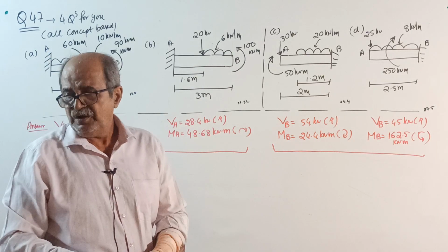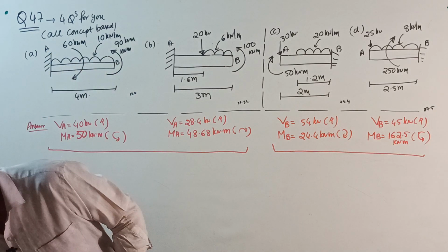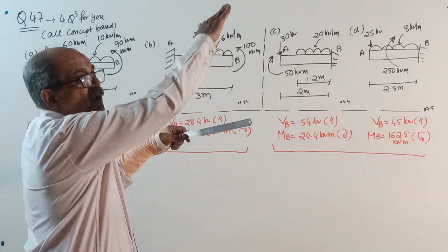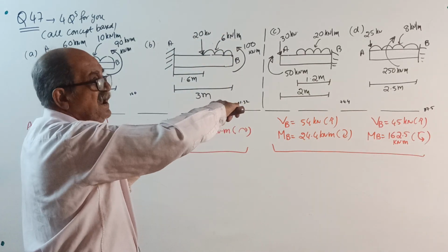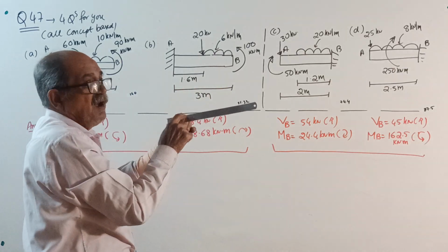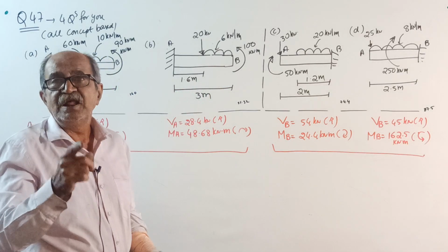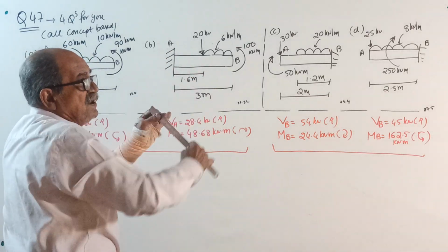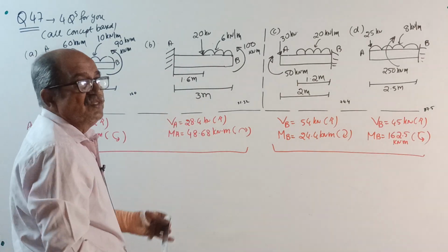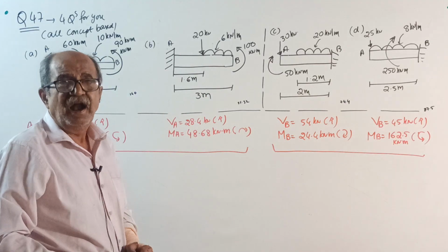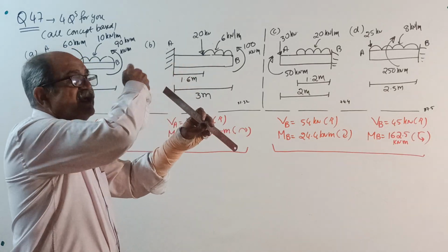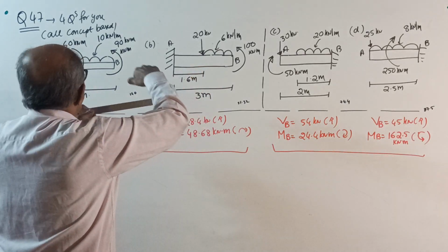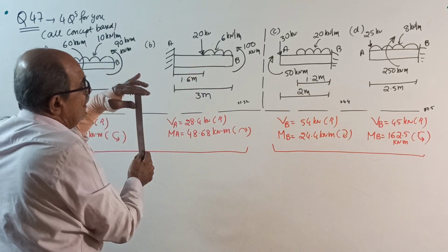Consider A and B. What all I tell, make a note. A and B are cantilever beams with left side fixed. I will hold here, left side fixed. When you apply loading on the beam, any type of loading, it will rotate about the fixed end, as I always told. You should consider rotation about the fixed end. So where I hold the fixed end, the loading will try to rotate in the clockwise direction, this way. Therefore, if only loads are there, 100% reacting moment will be anti-clockwise.